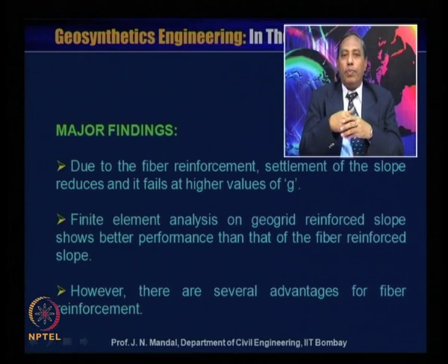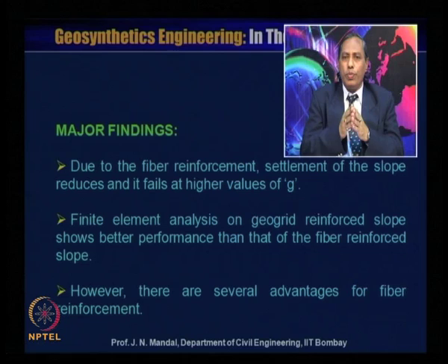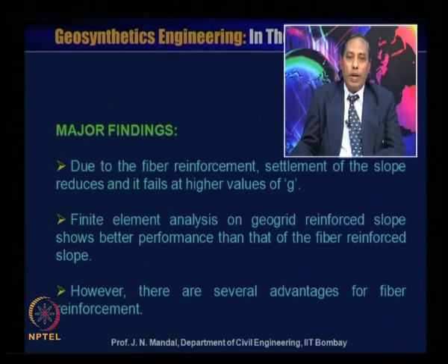So, what are the major findings? Due to the fiber reinforcement, the settlement of the slope reduces and it fails at a higher value of G. Finite element analysis on the geogrid reinforced slope shows better performance than that of the fiber reinforced slope. However, there are several advantages of the fiber reinforcement.